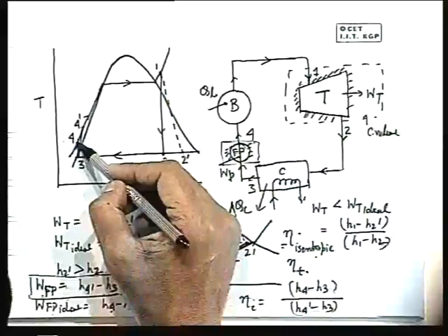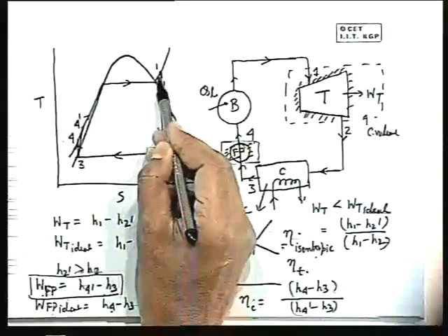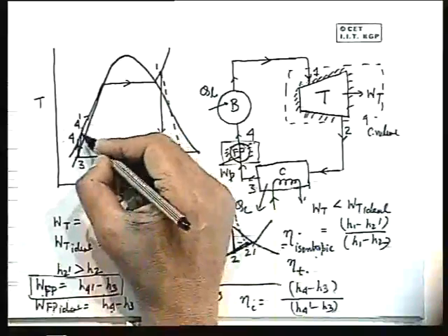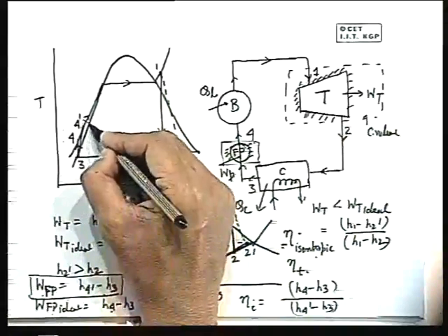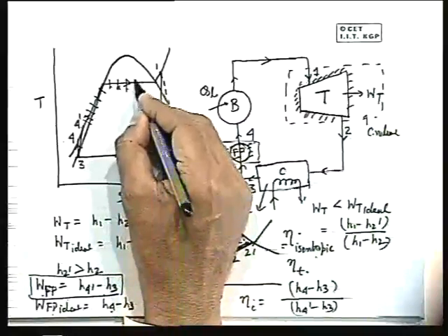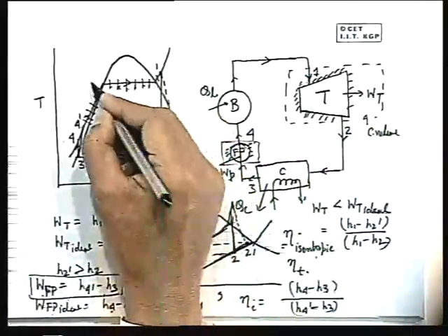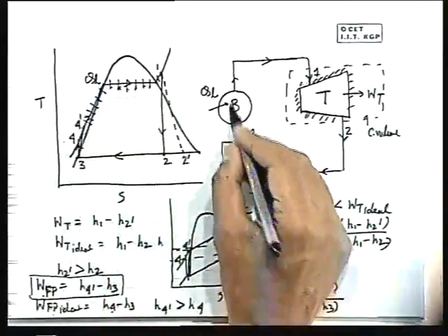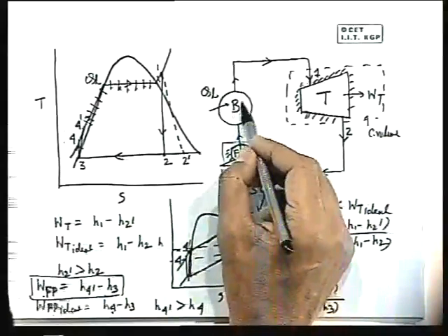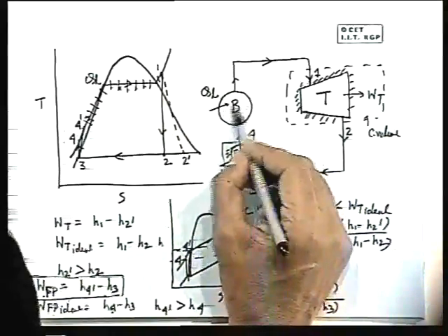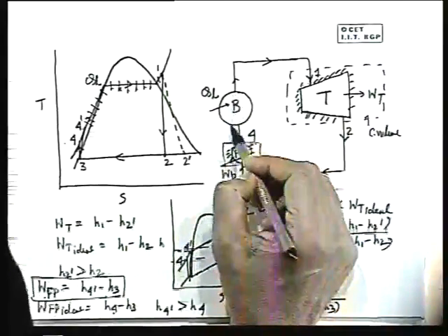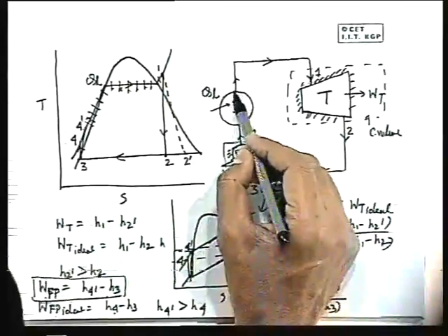For example, here if you see the boiler, the ideal process which is envisaged is a constant pressure heat addition. That means, from 4 dash for example, we add heat at constant pressure. This is the heat addition process, that is QB. And in a steady flow process, there are various components in the boiler through which the steam passes. There are a number of tubes, headers through which the steam passes, and ultimately water is converted into steam, and steam is taken up.